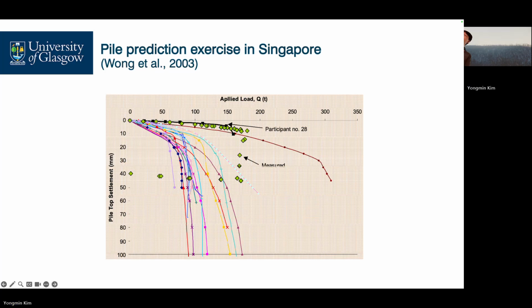No. In your numerical simulations, increase your loading, then see what happens. And then you can increase your pile diameters. And then increase your pile length and see what happens. And then discuss with your owner, with your results.